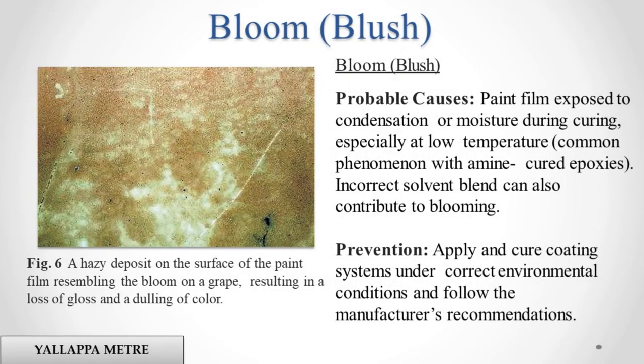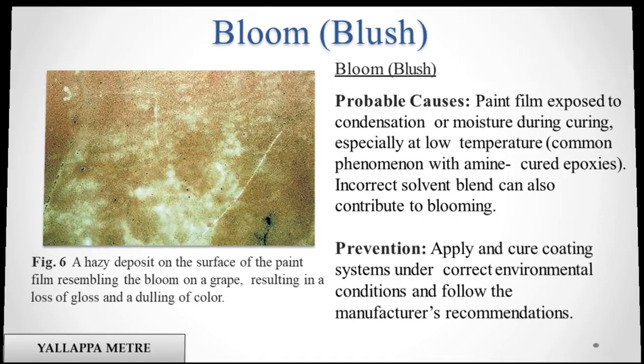Bloom, blush. Probable causes: paint film exposed to condensation or moisture during curing, especially at low temperature, a common phenomenon with amine-cured epoxies. Incorrect solvent blend can also contribute to blooming. Prevention: apply and cure coating systems under correct environmental conditions and follow the manufacturer's recommendations.